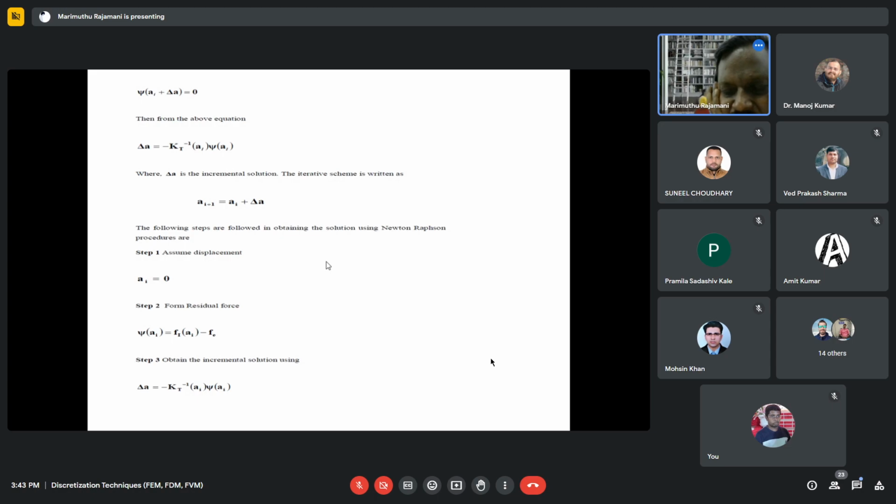That is a convergence study. And I would suggest the other one, error estimation and adaptive meshing, where it is not necessary to go on refining until convergence, but it reaches some level of finite element mesh and stops there.